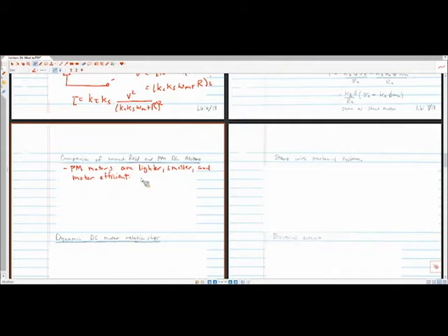How much voltage could she have put to that? Because she was just keeping it really low for the demonstration. Well, it's already busted, so she couldn't have hurt it, besides causing a fire, I guess. I don't know. That motor's rated for 24 volts. Now, when I caused this thing to smoke, I obviously exceeded one of those limits, right? I had a current supply and I sent too much current through it. It's rated for, I believe, 24 volts and 1.5 amps, and I must have gone over 1.5 amps.